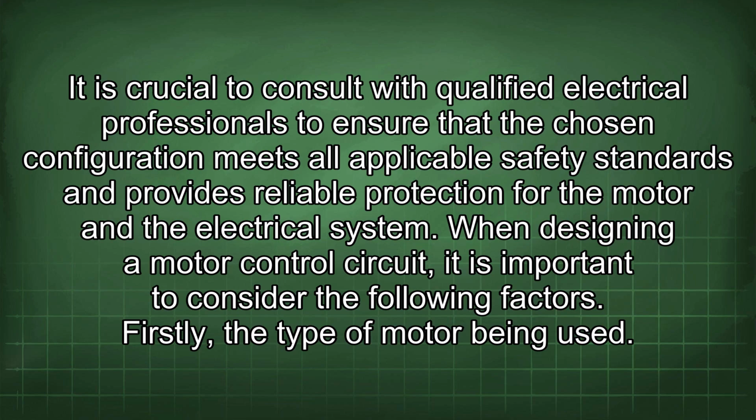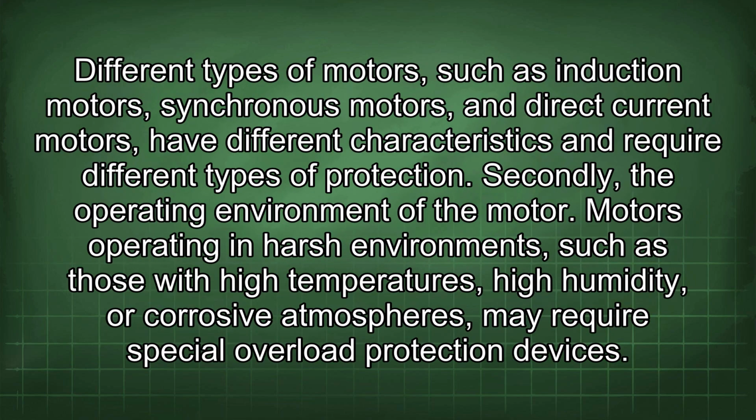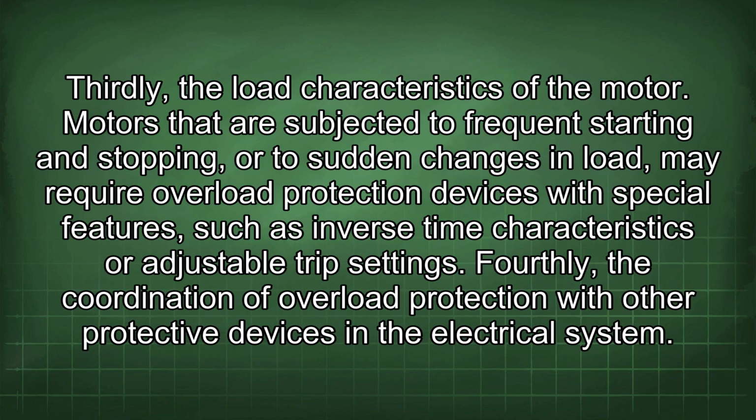When designing a motor control circuit, it is important to consider the following factors. Firstly, the type of motor being used. Different types of motors, such as induction motors, synchronous motors, and direct current motors, have different characteristics and require different types of protection. Secondly, the operating environment of the motor. Motors operating in harsh environments, such as those with high temperatures, high humidity, or corrosive atmospheres, may require special overload protection devices. Thirdly, the load characteristics of the motor.